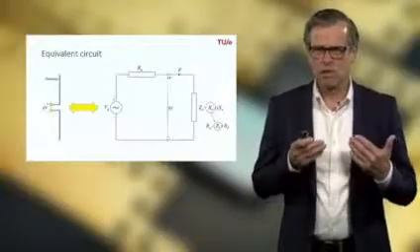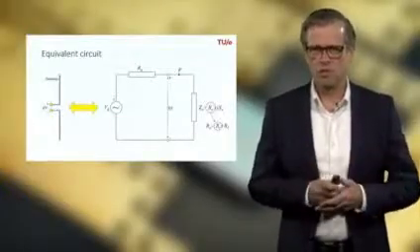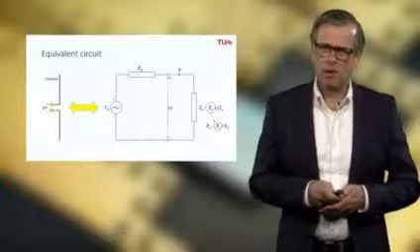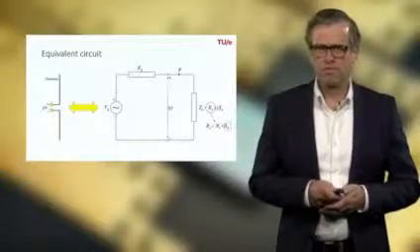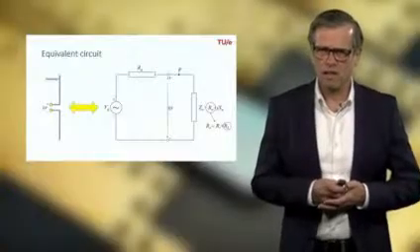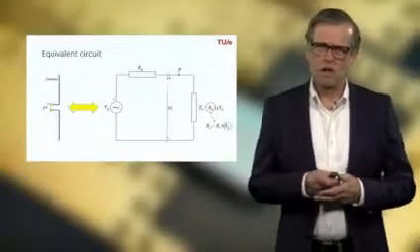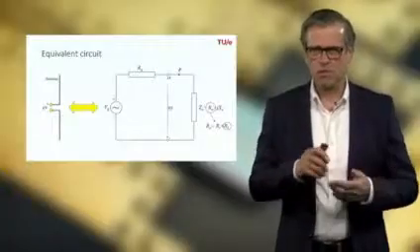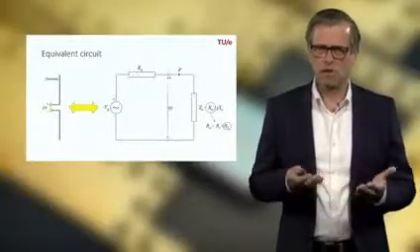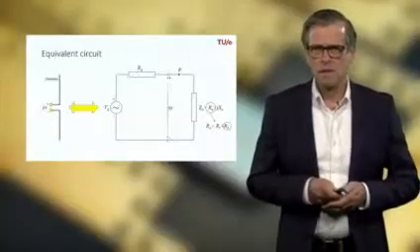So it's not a loss per se, but it's something that you want. The antenna should radiate. But the real part also includes a loss term. So these losses, RL, are related, for example, to ohmic losses that you might have in metal conducting surfaces which are part of your antenna, or dielectric losses, as to say.